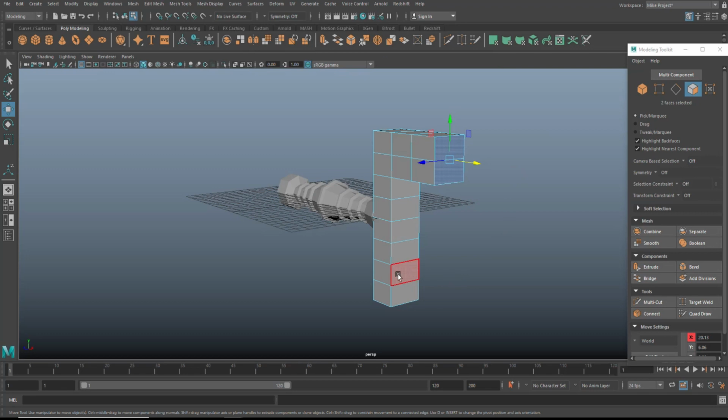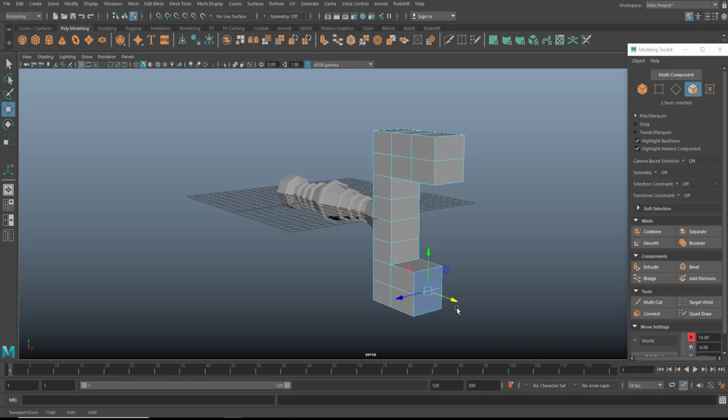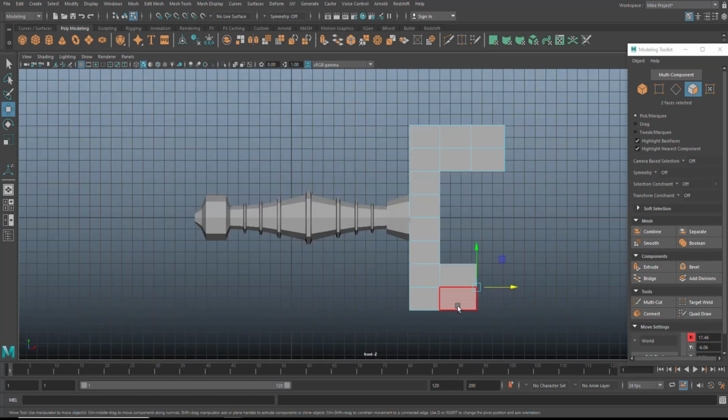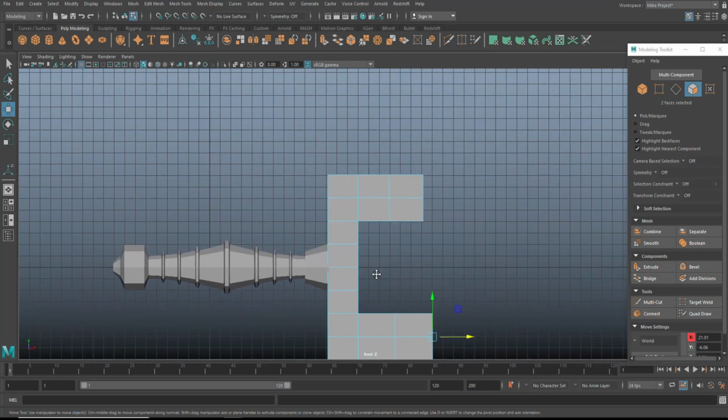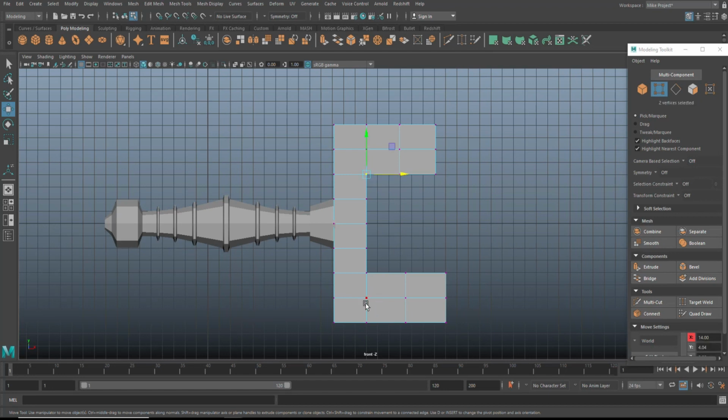And then we'll jump in here. Control E, pull that out. And we'll hit G to repeat and W to pull out. And let's do a little bit further. Okay, now that we have that, we can start to play with the shape. So we're going to go to vertex. We're going to take these two, and we're going to kind of bring that forward. Yeah, and we'll worry about the line flow in a second. I'm not worried, I'm just focusing on the shape right now.